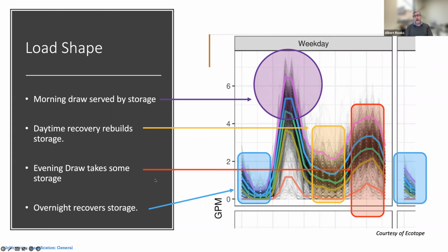of that big tank of water, we'd want to be able to size the heat pump capacity to recover it in maybe 3 hours, 4 hours, 5 hours, 6 hours, 7 and 8 hours, depending on the building type and when that secondary peak is going to happen, and if that matches up with a weekend profile. But essentially, that's what we're doing.